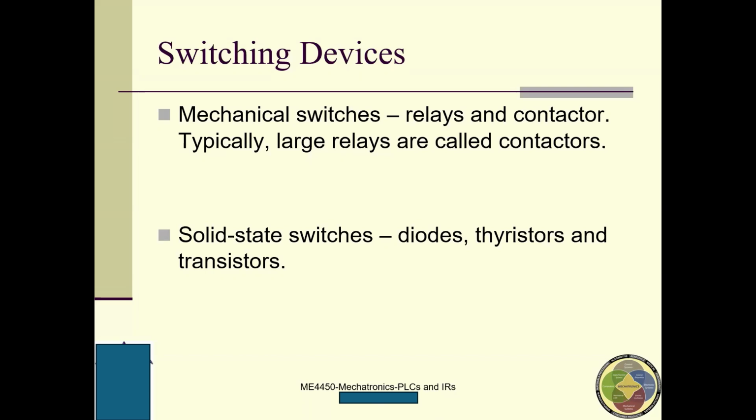This is A, and we have this gate, and we have this K. So this symbol is a three terminal, four layer electronic device. This is a gate. This gate controls whether the current goes through or not, from A to K, I'm sorry.